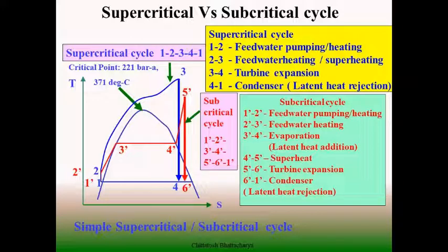At the same time, there are more statutory restrictions related to heat transfer rate, so the tube materials must be strong enough to withstand high temperature oxidation chances, and we have to see that the heat addition is taking place in a phased manner, so that the transition from water to steam is smooth.